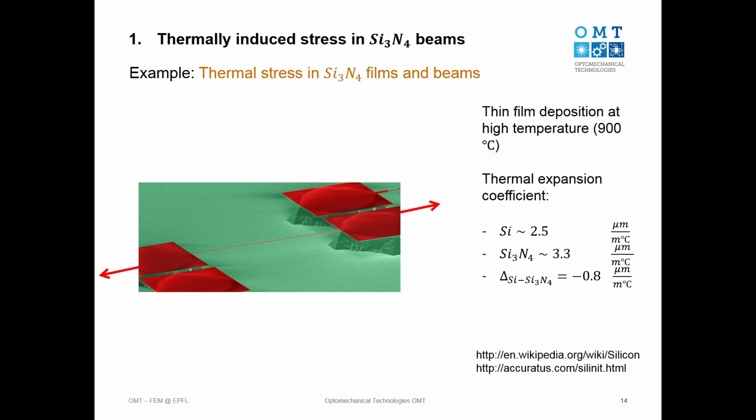So this stress that comes from the thermal expansion coefficient mismatch is called thermal stress. And we're going to calculate how much of this stress, if you start a wafer at 1000 degrees with these two at equilibrium and we cool it down, will be induced into this beam. Okay? Sounds fun, huh? So these values, I take them from Wikipedia. Unfortunately, and you can do the same simulation.